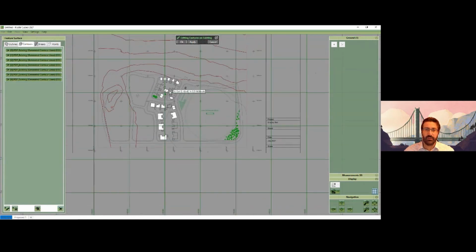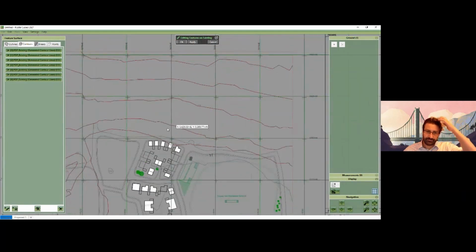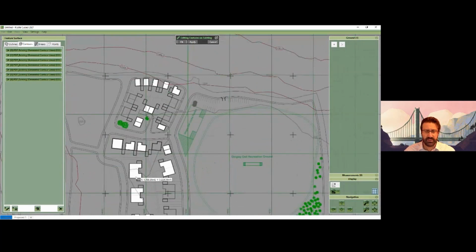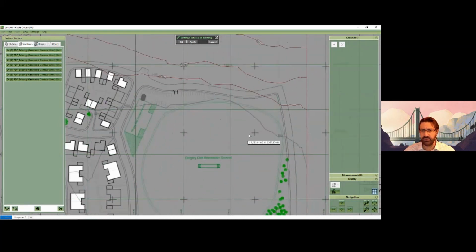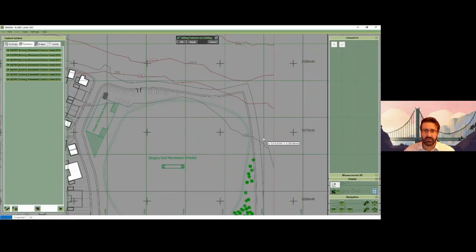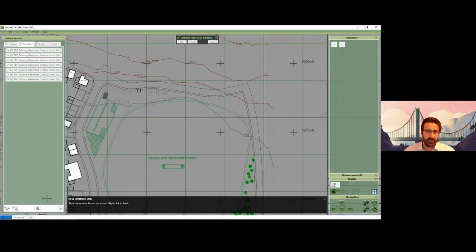So the other thing is, if you've brought in contour lines like this, in this situation, it's brought in all but the last one. That kind of thing is a bit typical with extracting from PDF, that you might not always get 100% of the data, so you need to check. So I might trace this last contour at 168, and then it will give us an opportunity to demonstrate the new tool with that set of contours.